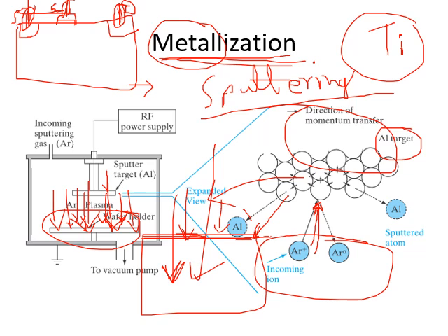So some barrier will be placed before copper metallization is done. Like a titanium barrier is pasted first, and then copper is pasted, so that the copper cannot diffuse into the silicon, right? Followed? Did you follow how this is done?